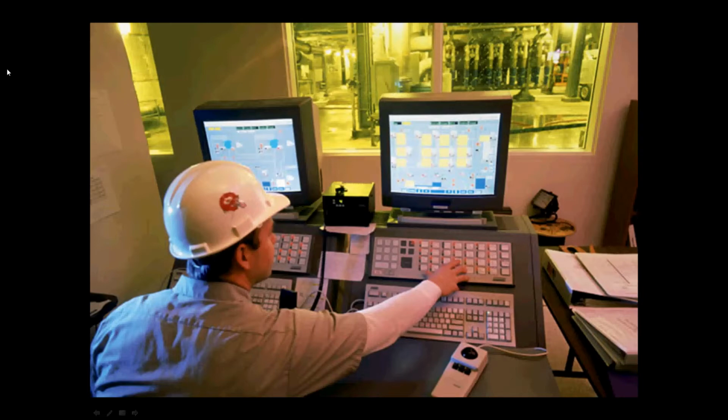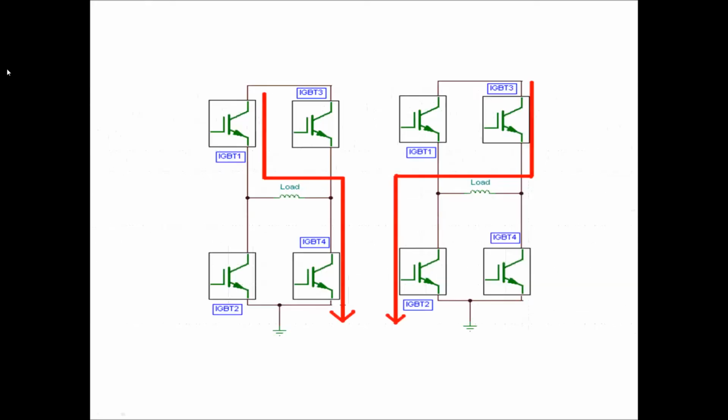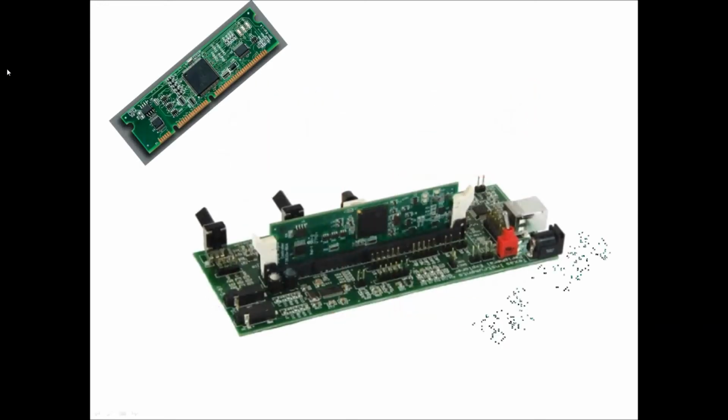Setting the timing parameters like on and off time is a complex task and cannot be achieved with high precision. The aim of this project is to develop a fully automated control system for monitoring of induction heating systems. Using the code for sine triangular modulation, a varying PWM is generated which is applied to the full bridge IGBT module so that it can provide an equivalent sine wave at the load. The feedback circuit of the control system helps in increasing the power efficiency of the system. Low pass filters and the feedback circuit are implemented as an algorithm in the DSP, which helps in reducing the losses and improves the reliability of the system.